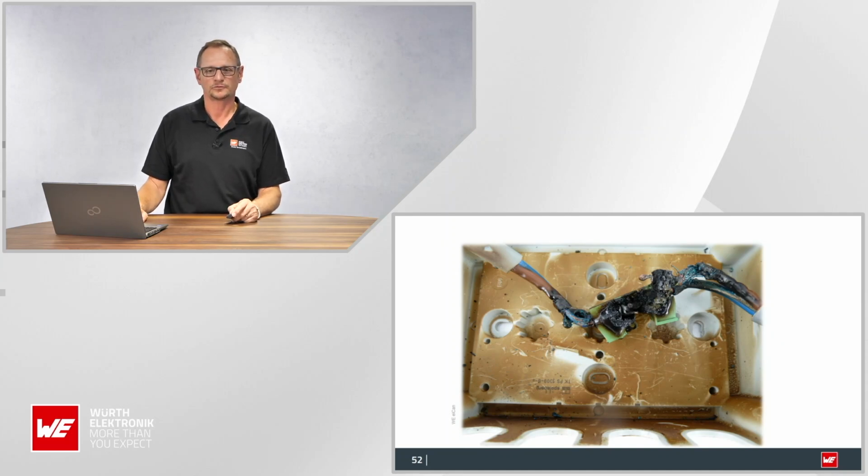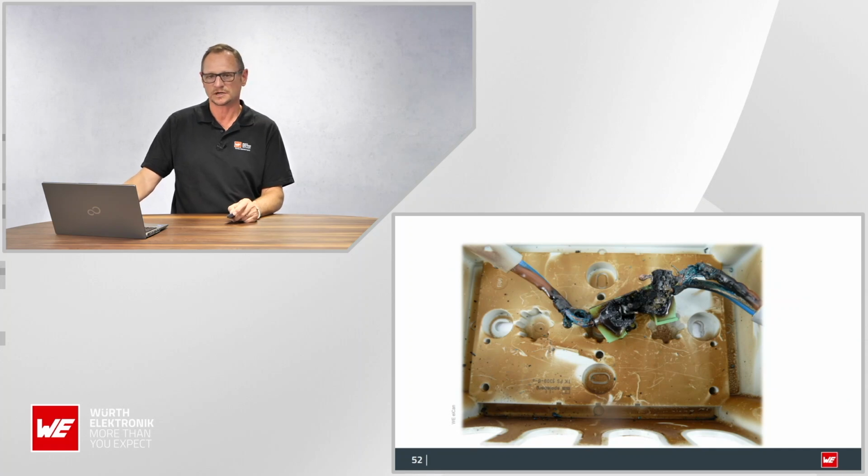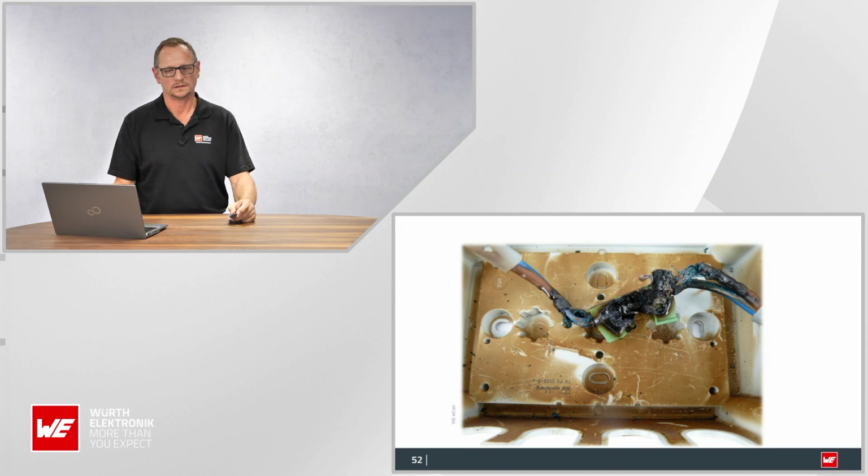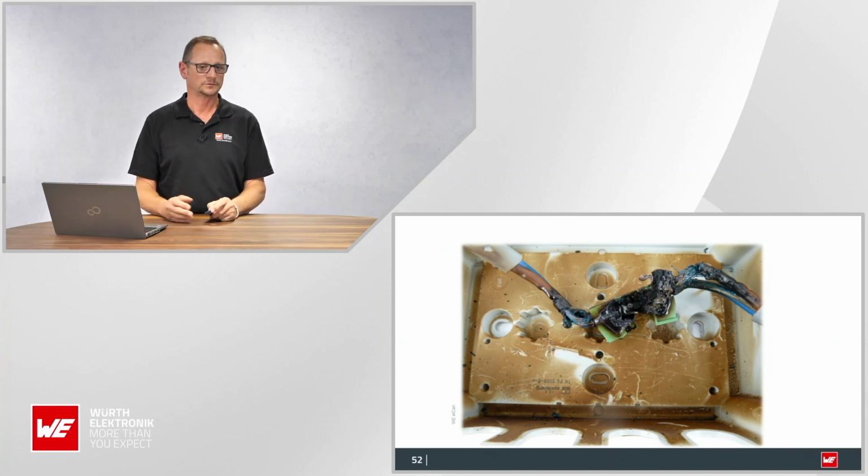And also about derating, we have a nice application note on the web, which is free to download and really helpful. In addition, we have also been looking at what happens if you have a pulsed signal or a pulse on your cables, especially in terms of inrush current. If you run a motor, the current can reach up to 6 times the nominal current.